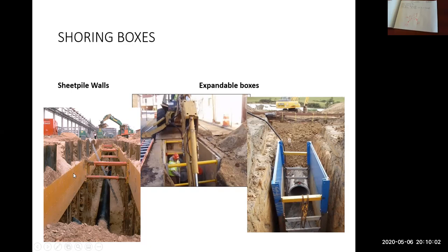So with this one, it's slightly different. It's not a shoring cage that you could pick up and put on a truck. It's built with sheet pile walls. So there's individual steel plates that are pushed into the ground and they interlock together. So you can have an infinite length of trench that's shored with sheet piles. If you have enough sheets, you can continue to put them in the ground. Of course, you need them on both sides.